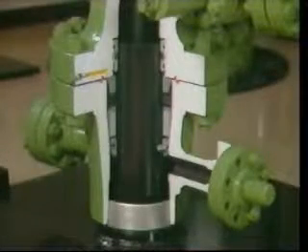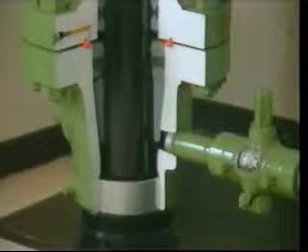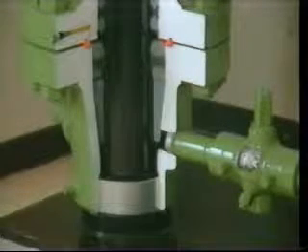Casing heads are available with either threaded or slip-on weld bottom connections. One advantage of the weld bottom is that the topmost casing joint can be cut to the desired height after cementing, ensuring that the wellhead will not be excessively high above ground level.